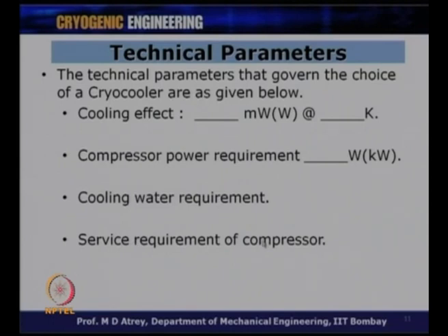Maybe after 10,000 hours of working or 15,000 hours of working, this is required to be done, and therefore, one has to know what the service requirements are, because when the compressor is being serviced, your cryocooler will be down, and if your application, for example, is in health services, the downtime is very costly. So, one should be aware of such parameters, and of course, the vibration level and the cost which I have talked about, all this will constitute the technical parameters, or it will govern the choice of a cryocooler to be used for a particular application in mind.